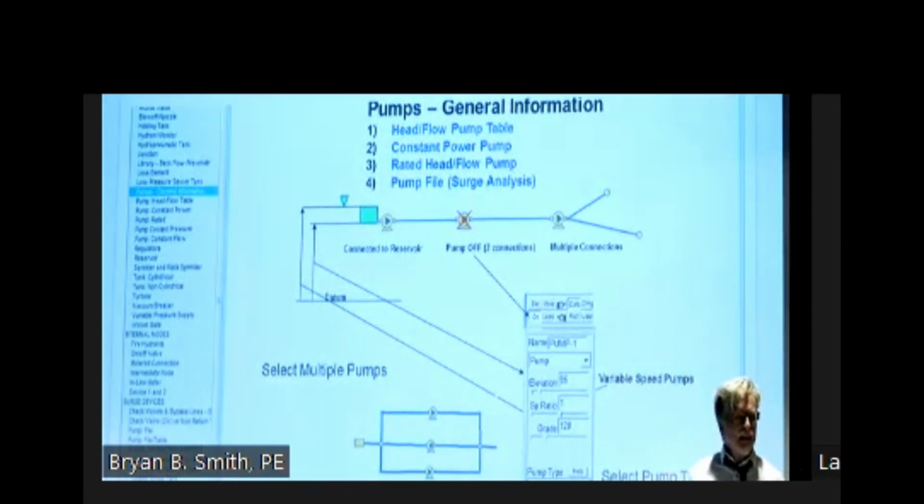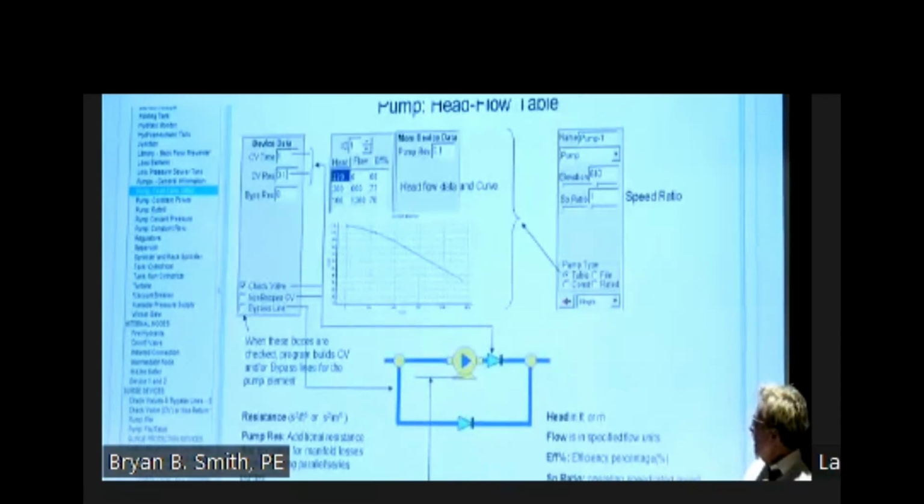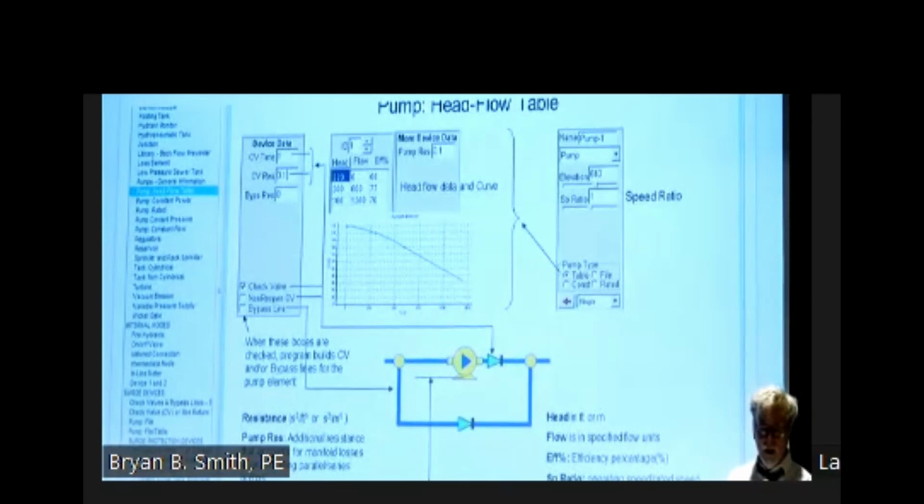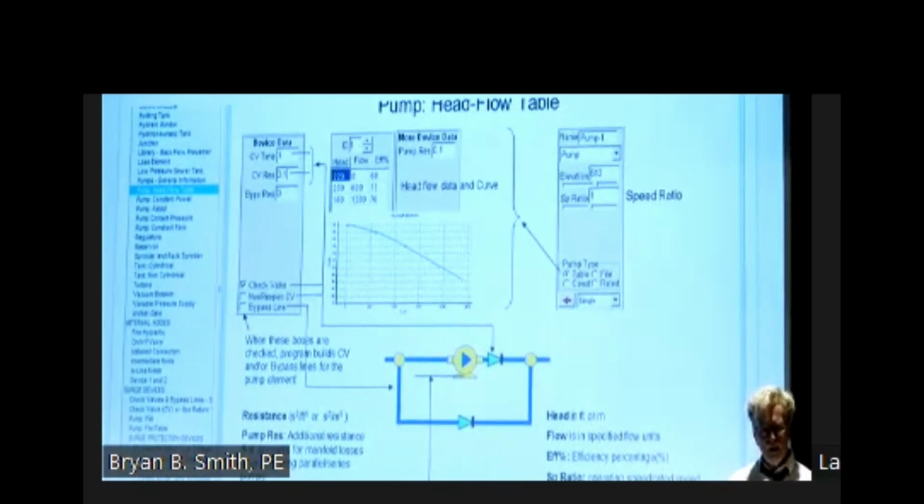In some cases, I need a pump bypass control valve or check valve. Everything about our system goes into the model. The best bet is to have the actual pump curve, and then we create a pump file and add in the pump inertia.